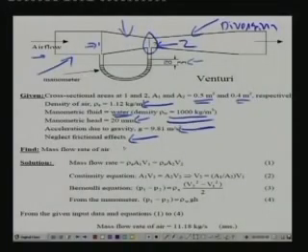First, what is the required output? We have to find out the mass flow rate for this venturi, which shows a manometric head of 20 mm. So, the equation for mass flow rate is rho A V: mass flow rate at any point is equal to rho into cross section area at that point and velocity at that point. So, you can write this expression for mass flow rate, and from the continuity equation, nothing but the conservation of mass equation, A1 V1 is equal to A2 V2, because we are assuming the fluid to be incompressible. So, rho A at any point is constant.